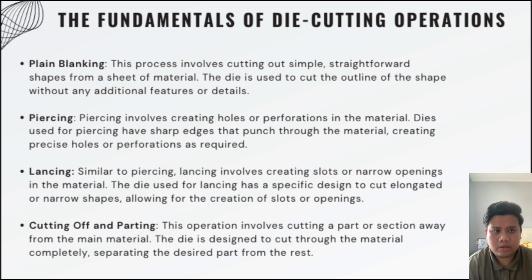Lancing. Similar to piercing, lancing involves creating slots or narrow openings in the material. The die used for lancing has a specific design to cut elevated or narrow shapes.